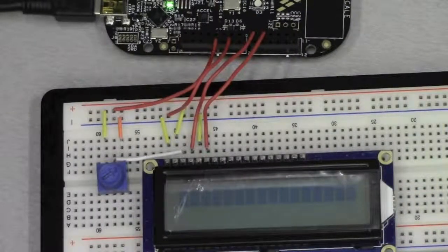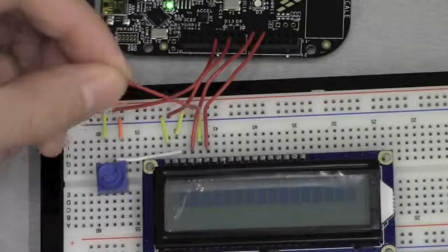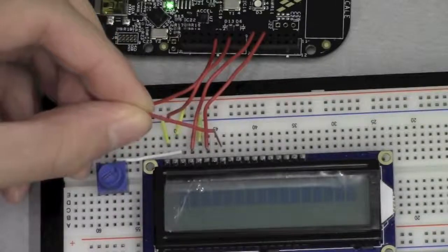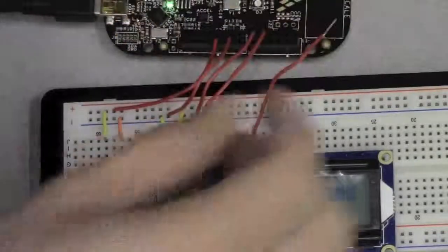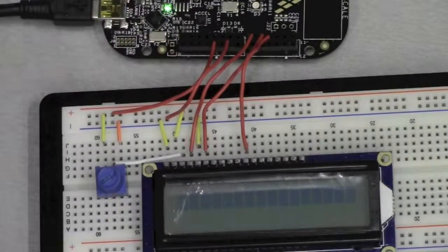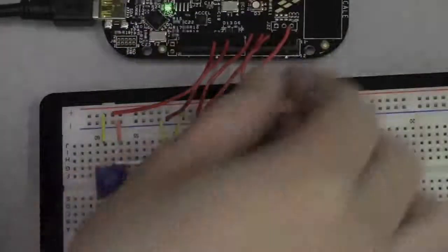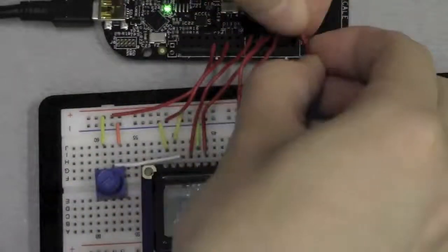So we're going to go ahead. Pin 11 is where we get digital pin 4 on the LCD display. So find pin 11: pin 6, and then this is 7, 8, 9, 10, 11. So 11 is right here, and we connect it to the next digital pin on the microcontroller. And we're going to attach the rest onto this. Connect this over to here.